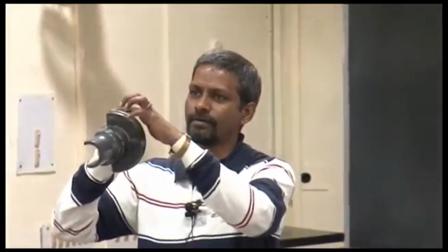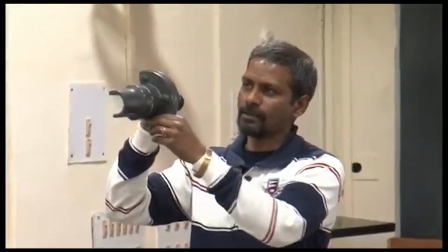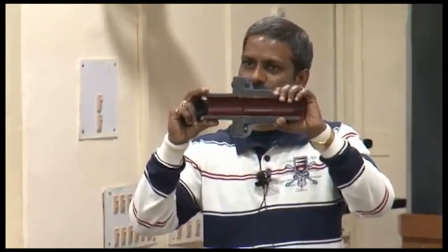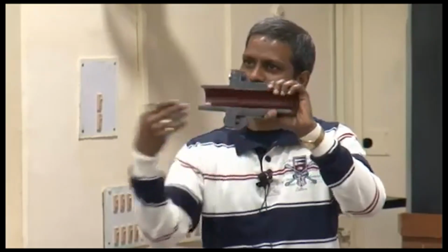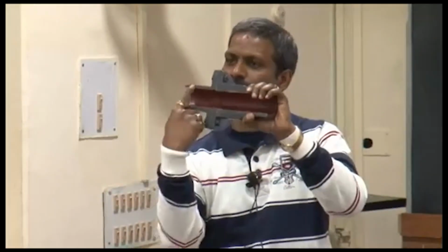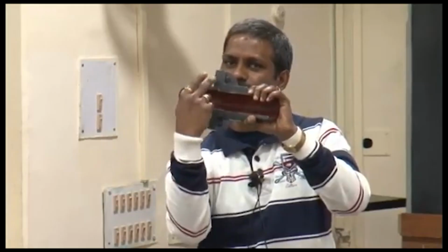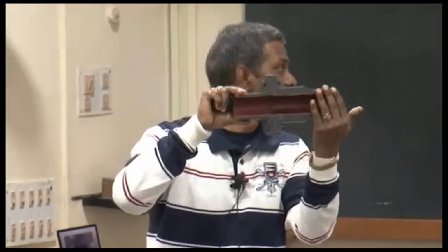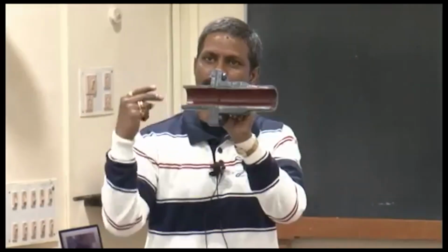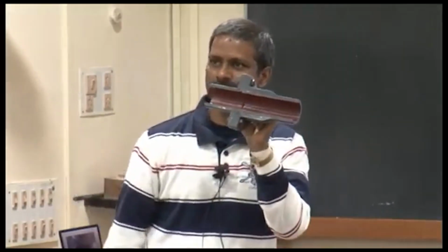First example. So you have fasteners over here. If your section plane is not passing through this, don't worry about that. Just section it and show what you see. So this part is getting sectioned. This part is getting sectioned. So the black part is hashed in your drawing. The red part is not sectioned, so it remains white.